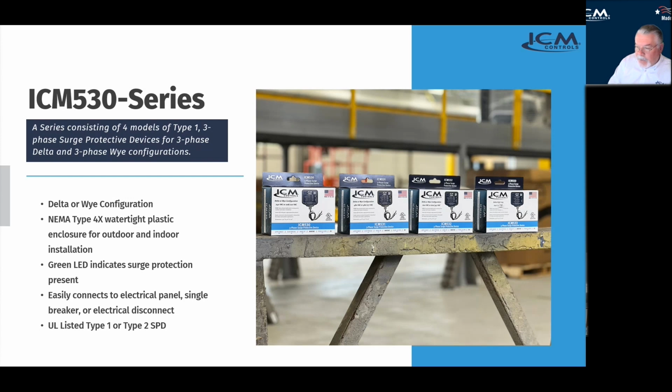So a type 1 for whole house panel will protect every breaker on the panel, but it has to be installed in a certain way. It has to be installed where incoming power comes in before it goes to the bus bars. So we've got a little short video to show you on that too. It's just hooking up one of these to a 3-phase panel. It's as a type 1. What Matt was doing in the video, he was doing that as a type 2.